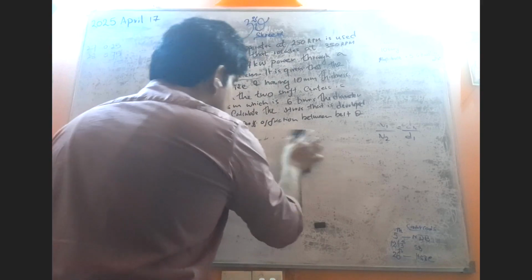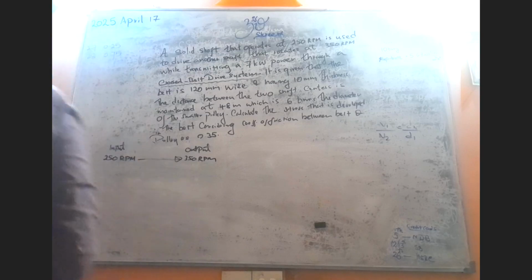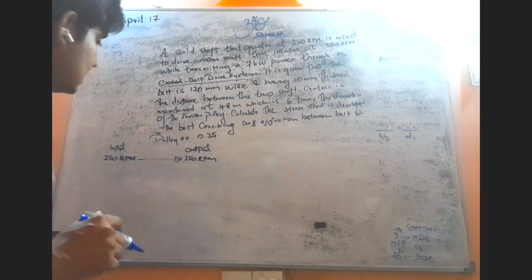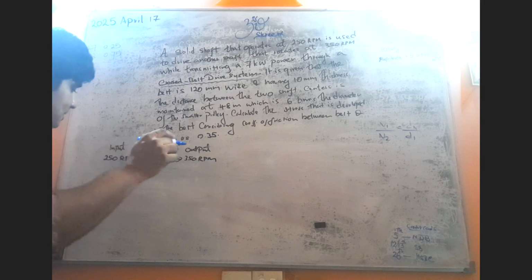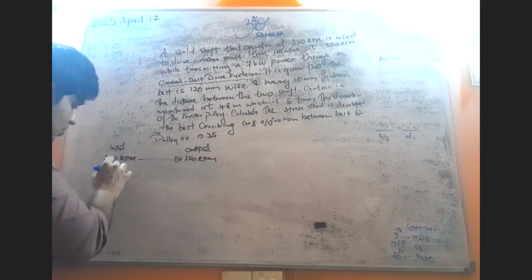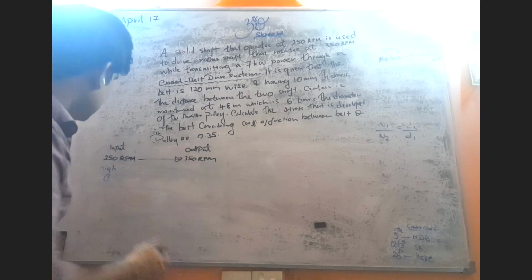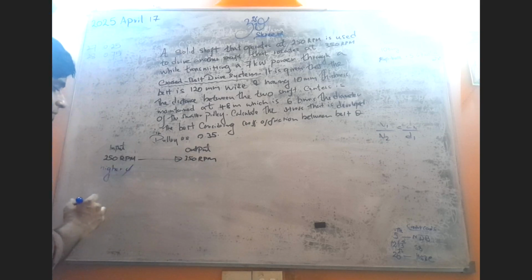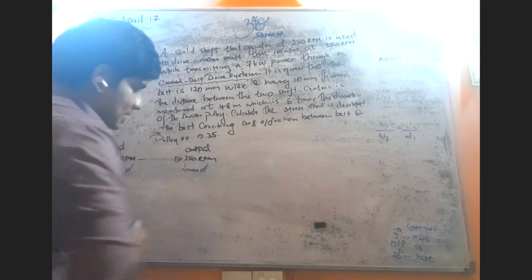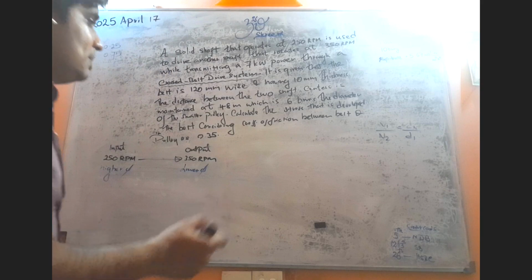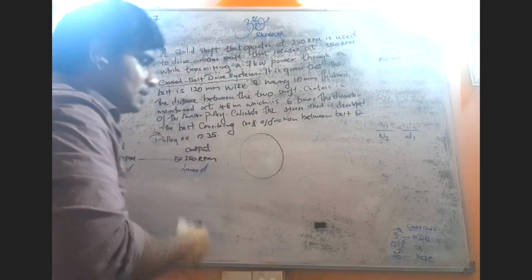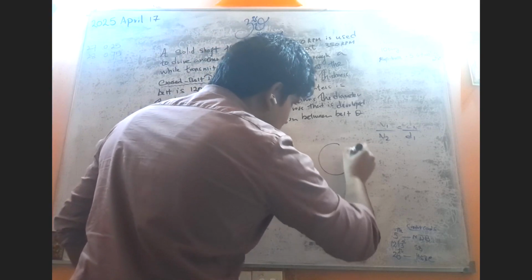All right. So now let's sketch this one. I am going to sketch the pulleys. Based upon that equation, with input 250 rpm, definitely this side diameter must be the higher diameter. You don't have to write these things, but just for teaching purposes, this side we can say the higher diameter. Why? Because low rpm there. Then this side lower diameter. So now let's sketch the belt drive system. This is the pulley with the larger diameter and this is the smaller pulley.